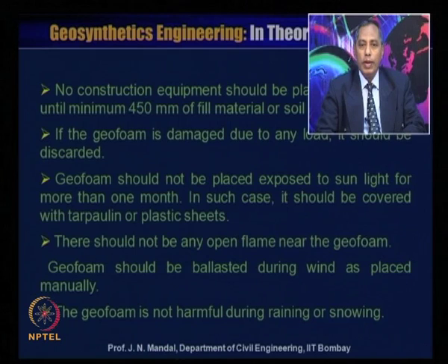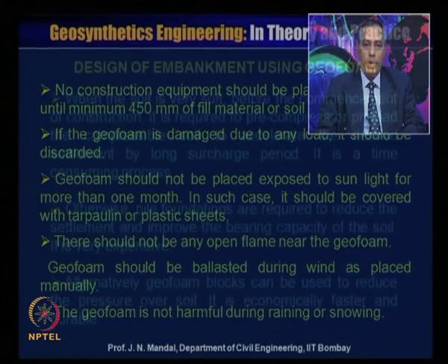Geofoam should not be exposed to sunlight for more than 1 month. In such case, it should be covered with tarpaulin or plastic sheet to prevent it from the ultraviolet light. There should not be any open flame near the geofoam. Geofoam should be ballasted during wind as placed manually because it is a very light material. The geofoam is not harmful during raining or snowing.